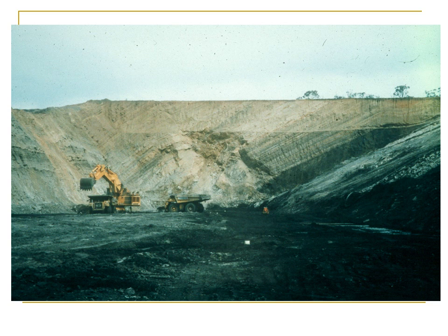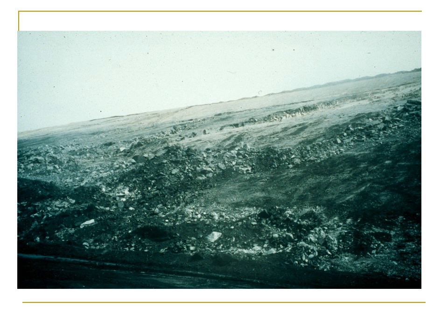But if we look at the wall to the right, which is called the low wall, if we look at that wall, we'll see the sliding mass. Here you can see the scarp or upper surface of the sliding mass, and this is all debris that's moving down the slope, and they've had to remove some of the material at the toe to try and keep mining operations going.